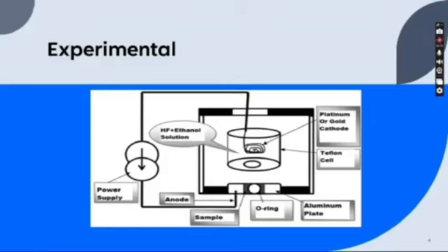Figure 1 shows the schematic diagram of the anodizing apparatus, consisting of the anodizing tray. This anodizing cell is connected to a stabilized power supply that delivers a constant current. It uses a metallic electrical contact on the backside of the silicon wafers, which is isolated from the HF ethanol solution by an HF-inert ring. Thus, only the front side is exposed to the attack of the electrolyte.